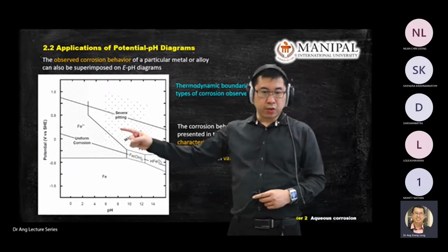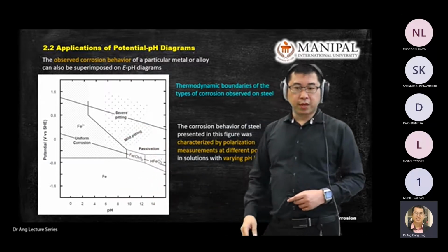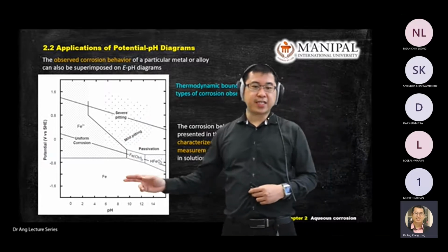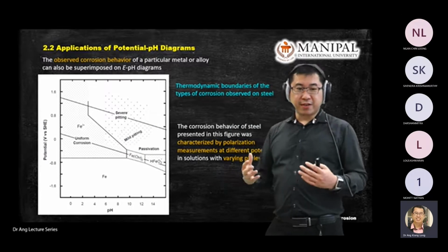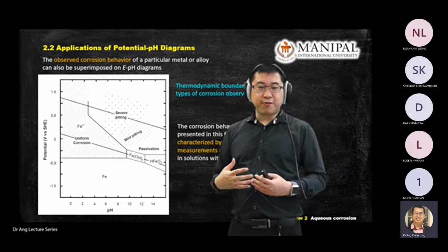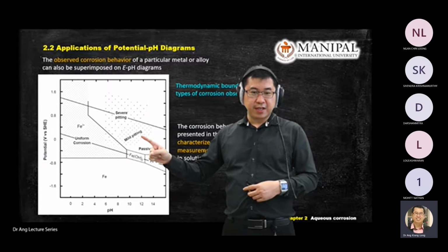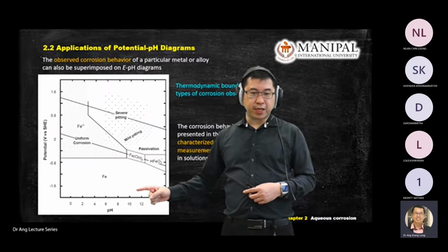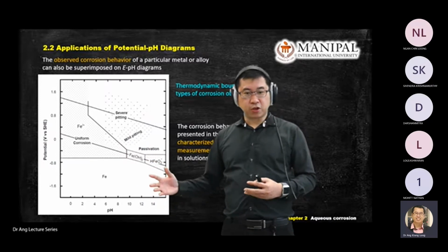Okay. So actually you can guess, right? By looking at the pH value, in common sense you know that when it is more acidic, the corrosion will be activated, and the process will become faster and faster. So as you read the pH value, let's say this point you project down is alkaline, more than 7, right? The corrosion will still happen, but in a slow manner.